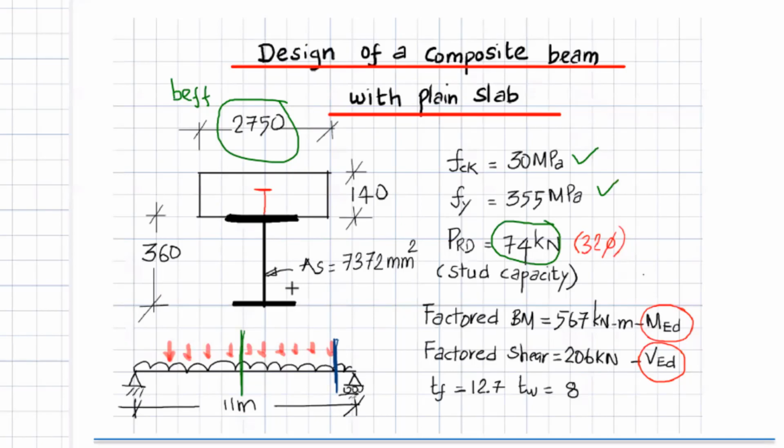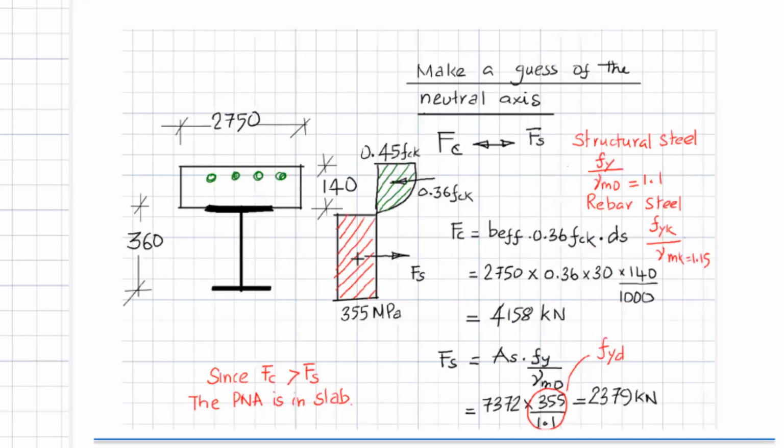Okay, next thing is, now I come to the stress part of it. What did we see? At the ULS, I assume all the materials reach their maximum, correct? So I draw the maximum concrete and the steel stress. Now, the governing principle for me is that the compression must be equal to tension. Because what is after all a moment? Two equal and opposite forces separated by a distance. Now, the compression component has to match the tension component.